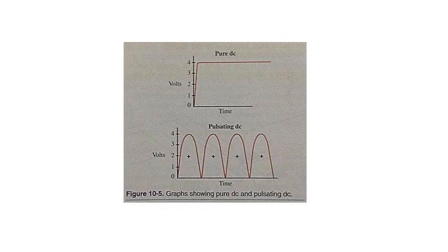The major difference between an AC generator and a DC generator is the use of slip rings in the AC generator and the use of a commutator, or split ring, in the DC generator. Both slip rings and split rings provide the electrical current connections from the armature to the generator load circuit.